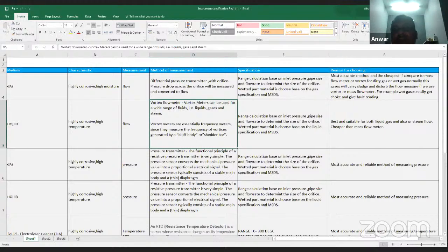operation after it is installed, after we run the stream and do a verification process. Then only will we come to a conclusion. Actually, this instrumentation validation determines the frequency that we need. So once you do the verification, from there you are able to determine the right calibration frequency.